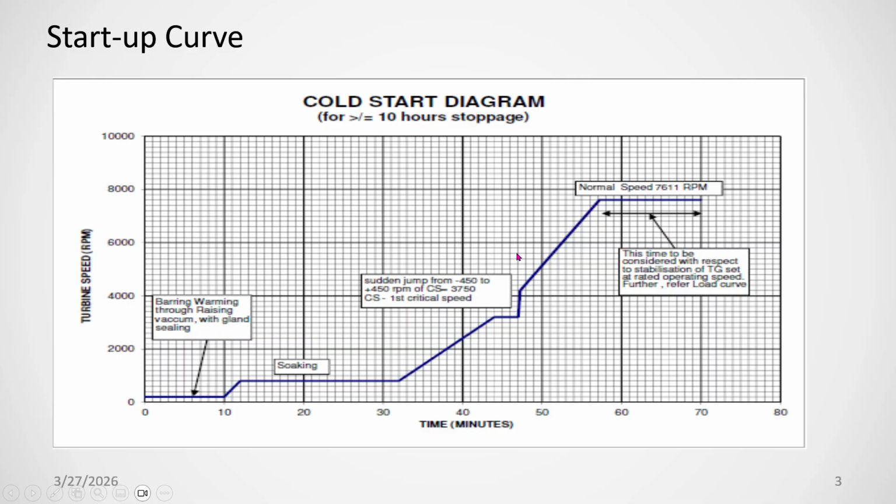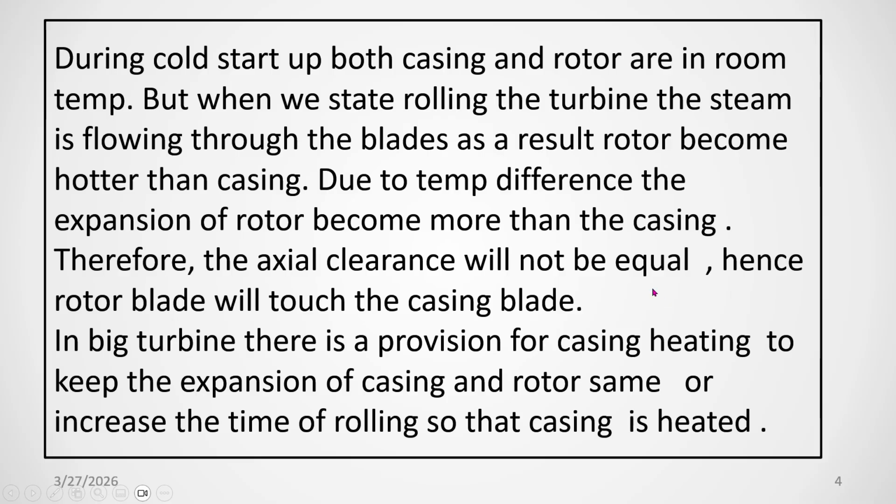Why are you doing this? Why is it taking so much time for a cold startup? Because when you are introducing cold steam into the turbine, the steam will pass through the blades, and the turbine rotor is rotating, so the tendency is that the turbine rotor will expand and quickly get to the temperature.